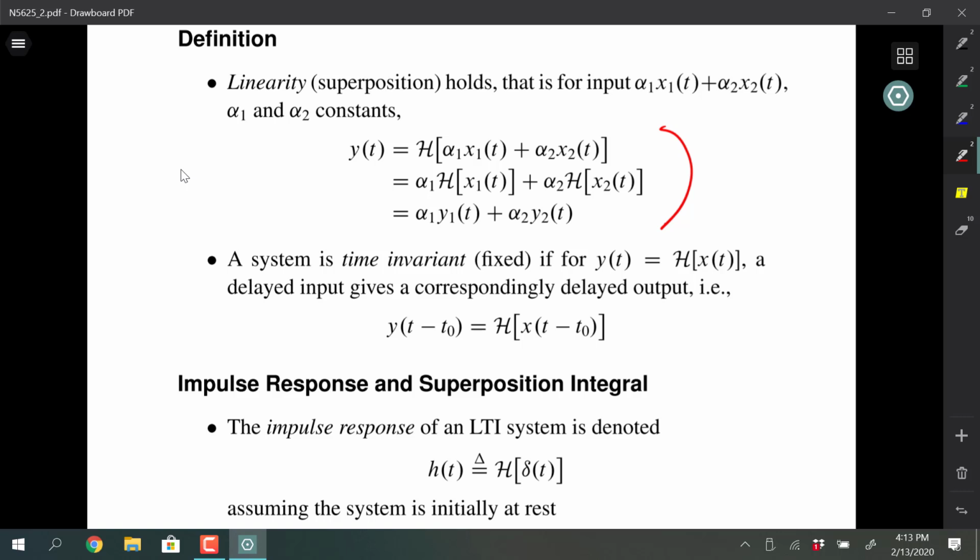Of course, it's never true in practice because you always will reach a limit where something breaks, like you drive an amplifier too hard. What happens? It rings. Well, not only does it ring, it starts clipping or something, right? It rails. Is it linear at that point? Can you superimpose two signals and get the sum of the output? No. But that's a practical limit, though.